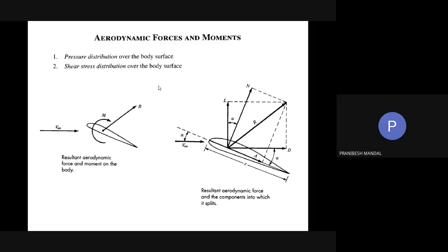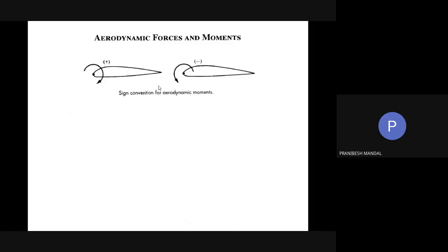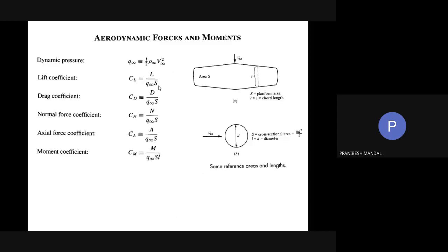And you see, all your force and moment coefficients depend on this V infinity. Your airplane design is actually based on this particular V infinity, because all these coefficients are designed with it. So if V infinity is always changing, your CL and CD are going to change always, as they are functions of V infinity.